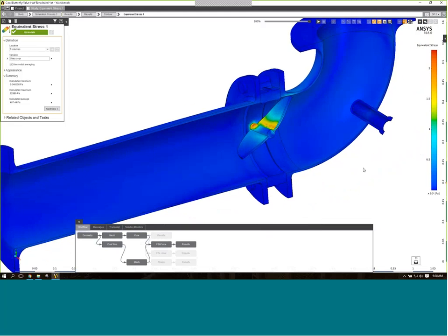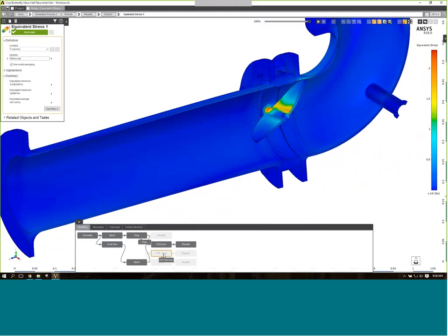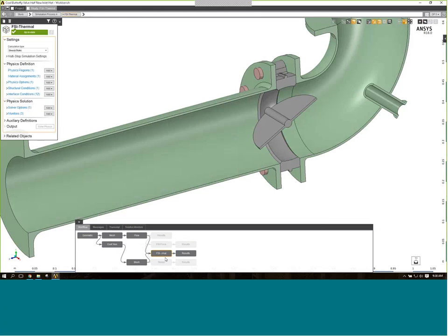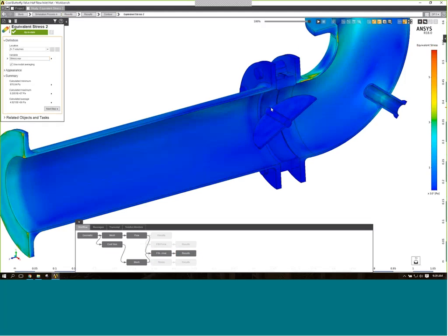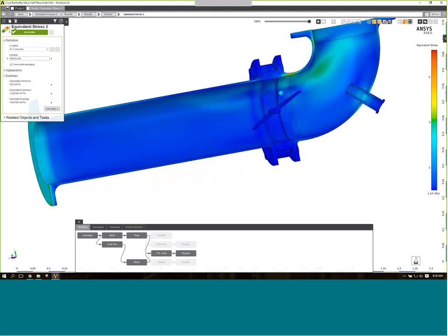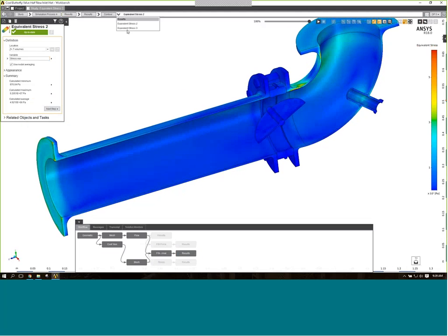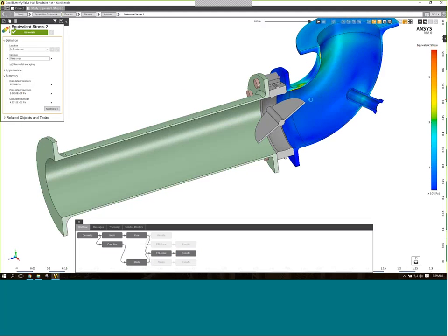Then I can go even further and I can say, well, I want to do another fluid structure interaction, but in this scenario, I'm going to do a physics coupling, but the physics coupling is going to take the solid temperature predicted by my flow simulation, and I'm going to map that to my structural simulation, and I'm going to take a look at my thermal stresses as a result of those non-uniform temperature gradients and identify where those hotspots are going to be, okay?